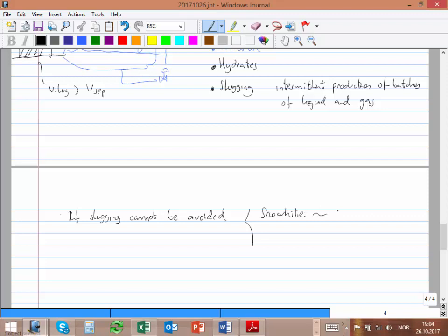This field is a subsea gas field that is 146 kilometers from the coast, and you have exactly that problem. Liquid water starts to drop out, and then these slugs happen, and then the separator has to receive these big slugs. That also will happen in block 2.